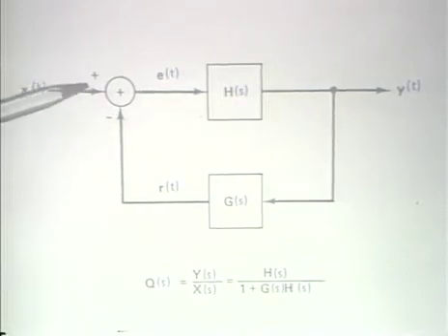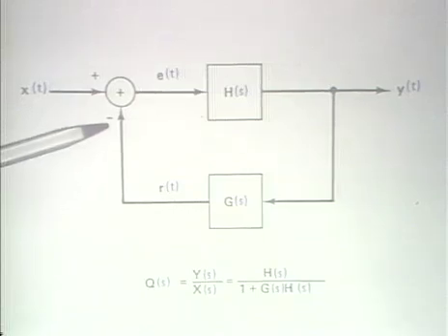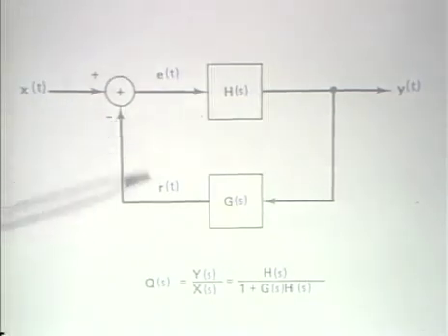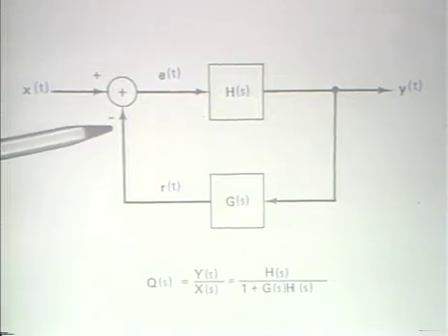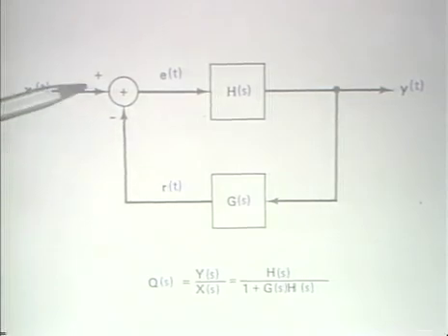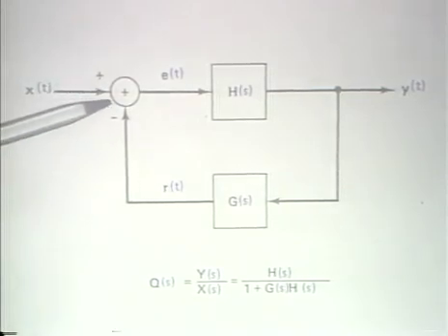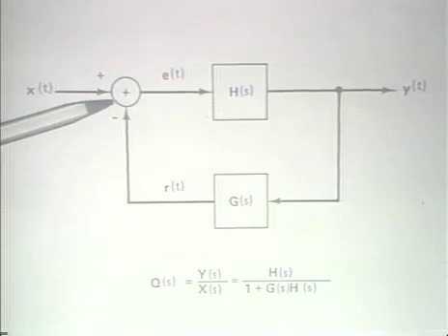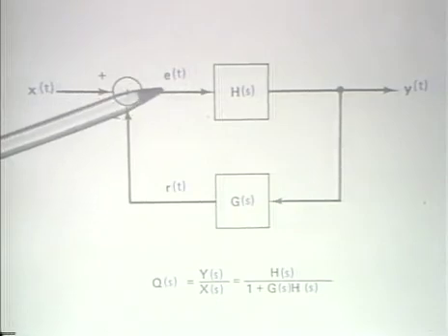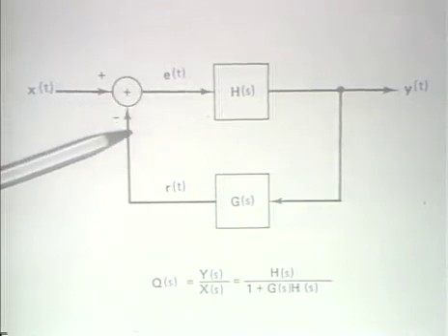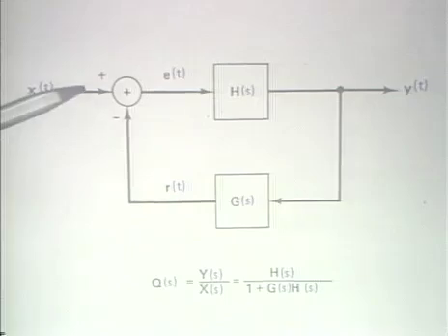And I draw your attention to the fact that what we illustrate here and what we're analyzing is negative feedback, namely this output is subtracted from the input, and that's done more for reasons of convention than for any other reasons. It's typical to do that, and appropriate certainly in some feedback systems, but not all. And the output of the adder is commonly referred to as the error signal, indicating that it's the difference between the signal fed back and the input to the overall system.